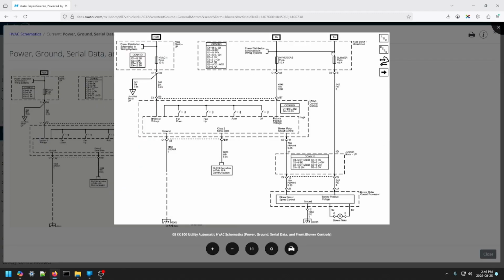We've got a fuse block, and it has two fuses, one for the blower motor and one for the HVAC control module. So go hunt those down, make sure those fuses are good, make sure there's power getting to them, etc., etc. So then what do we have here? We've got the HVAC control module, and there's other information you could dig around and figure out where that's located.